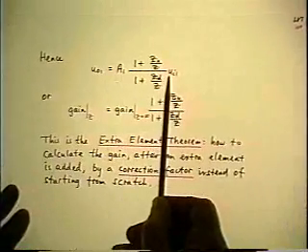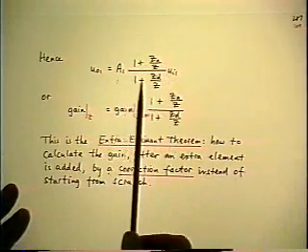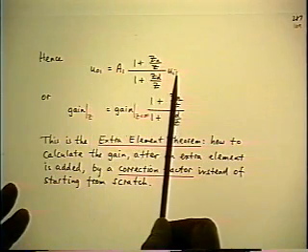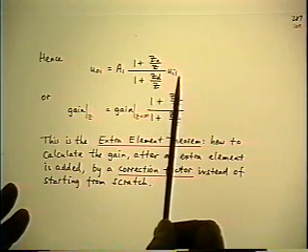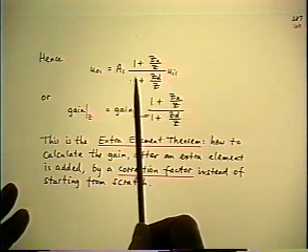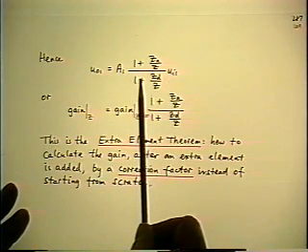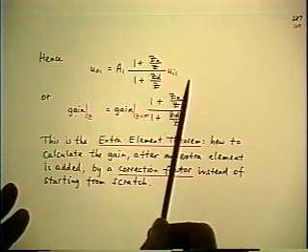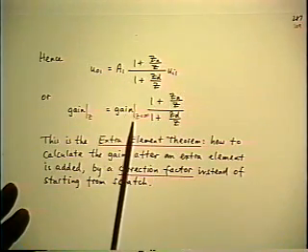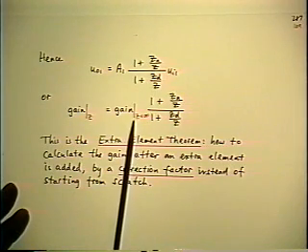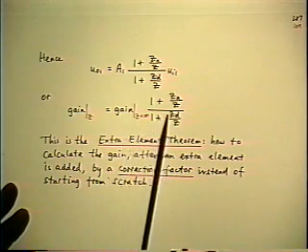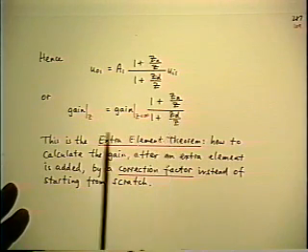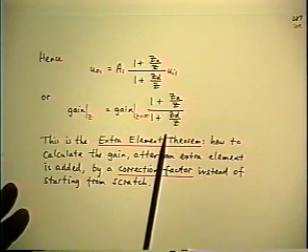you get this line, and you see what this says is output number 1 divided by input number 1 in the presence of the element Z is equal to A1, which is the same ratio of output number 1 to input number 1 before the Z was applied, multiplied by a correction factor. And that is the extra element theorem.